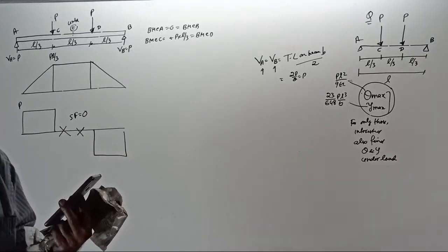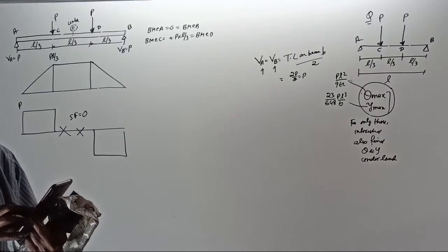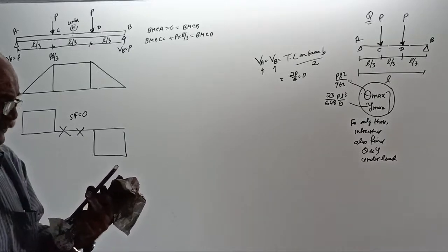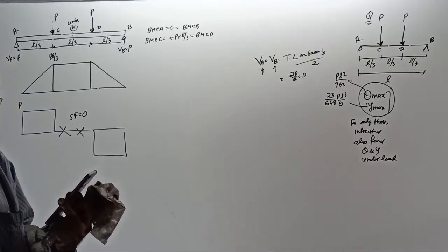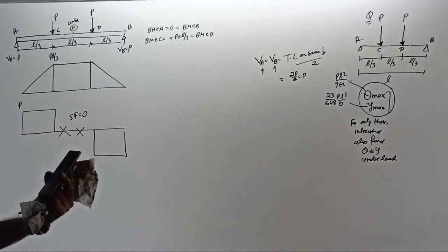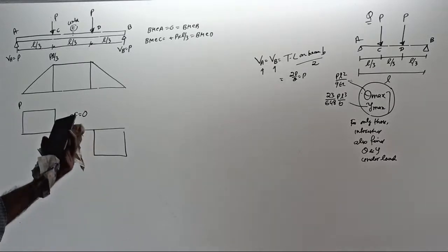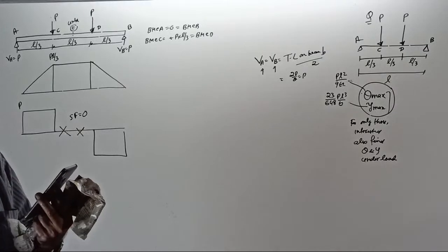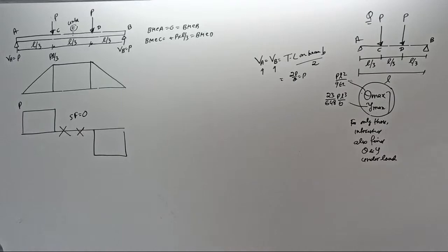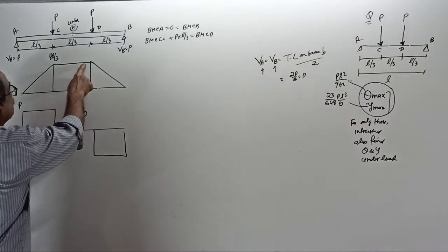Between the 2 point loads, shear force. No answer. This much time to answer. See the shear force diagram. You are not telling any answer. It is 0. And if the shear force is 0, then the bending moment is constant.